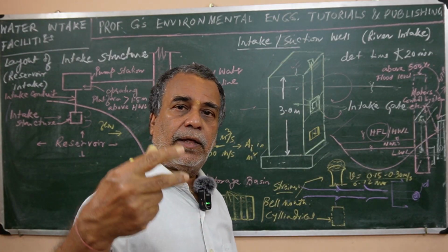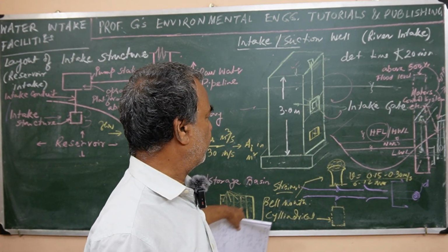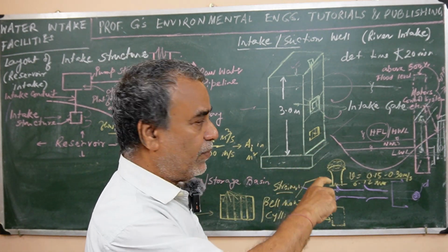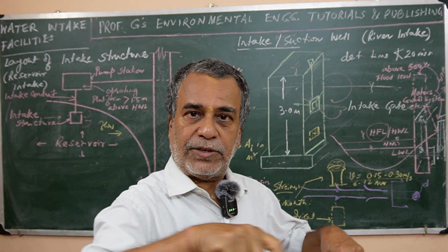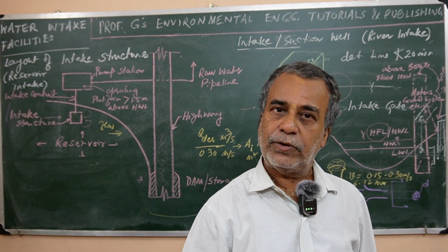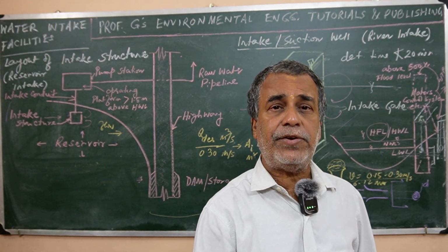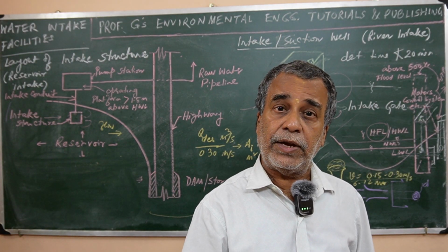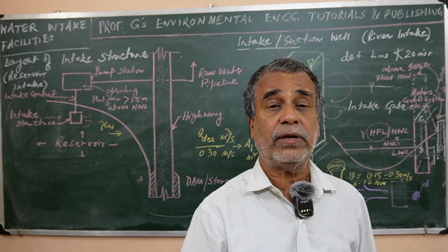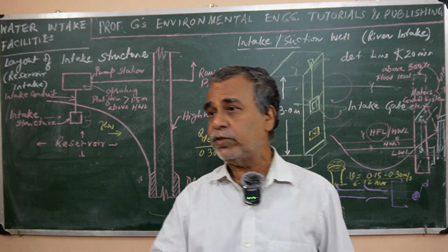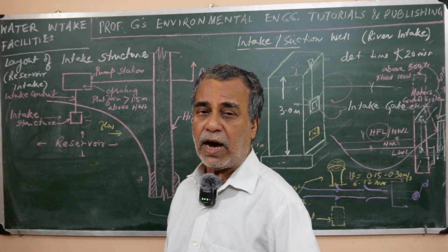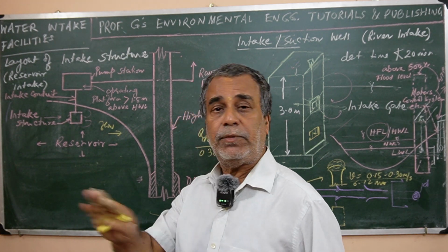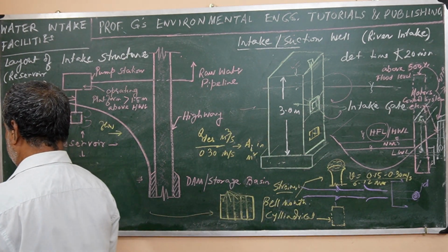In case of a tower intake, the gate may be like that. For other types of intakes, it may be a strainer type, that means in the inlet line, with the inlet conduit. Now when it enters the suction well, before pumping, there should be another strainer, the coarse strainer. The coarse means the materials which are unwanted for pumping must be eliminated.